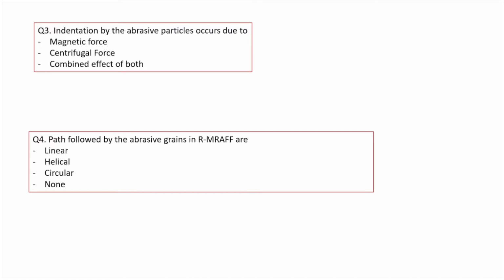So what will be the forces due to the reciprocation? One will be the radial force, one will be the axial force, and also due to the magnetic field, a magnetic force is there. The direction of the magnetic force and the radial force are the same, and the magnetic force will be perpendicular to the workpiece direction.